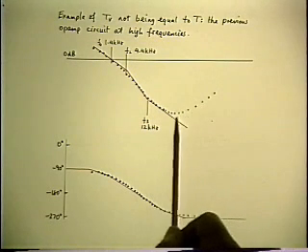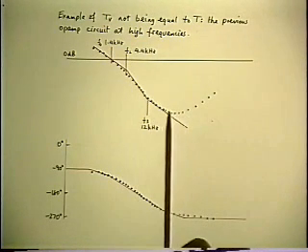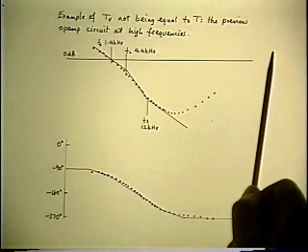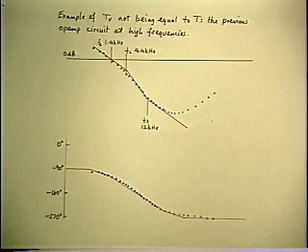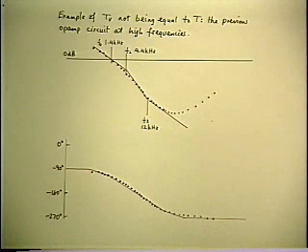For one thing, if you get measurements of loop gain that do this, it's not too likely that the loop gain really does that. Because we haven't seen any op amps whose gain turns around and comes back up at very high frequencies. In fact, we'd be very happy if someone could give us one of those. So it's not likely that the loop gain really is doing that.